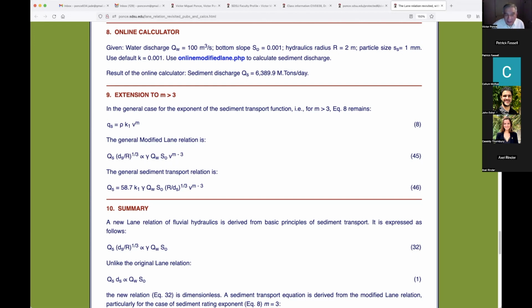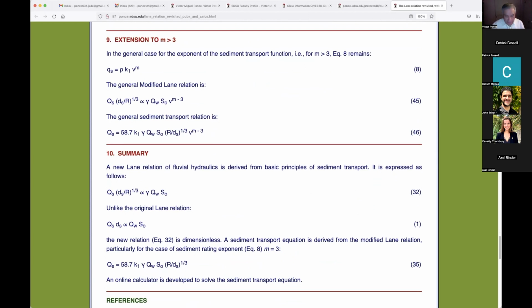There are things that cannot be precisely calculated. Sediment transport is not like hydraulics. I said this before, and these numbers are pulled out of the air, but they're good numbers based on experience. In hydraulics, you can make a 2% error, it will be fine. Not more than 2%. In hydrology, 25, 30% will be acceptable. In sedimentation, 100%.